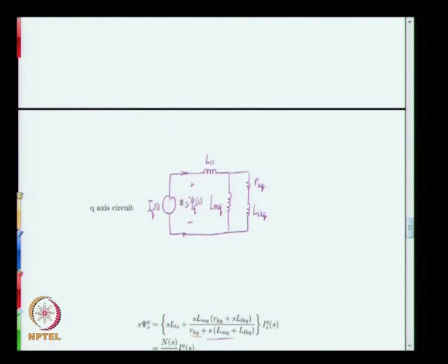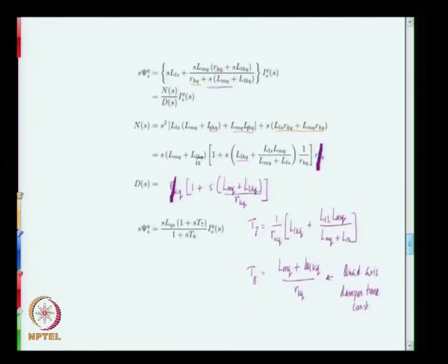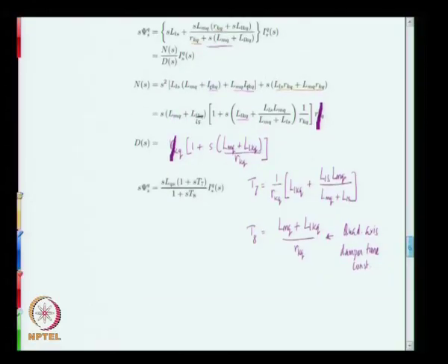In the denominator, if you open the armature side, then as seen by the resistance of the damper, the inductance is nothing but LLKQ plus LMQ, which is exactly what you have here. So here again the denominator term T8 can be arrived at by assuming that the stator terminal is open.